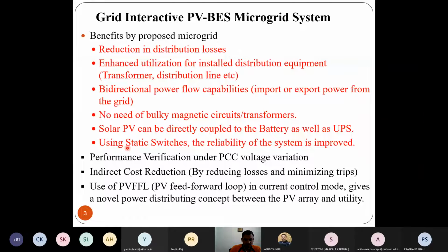And so by having relay and circuit breaker, they are having their own response time. I mean, there is delay, they will take 1 to 2 seconds or more to switch on and switch off to give the instruction. Here we are simply using the power electronic switches. They are having the response time in microseconds. So this way we can improve the reliability of the system.